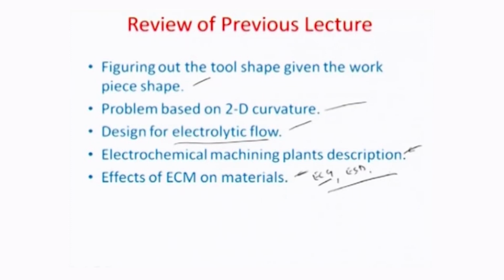After the review of these fundamental electrochemical machining processes, we will start over again and try to apply some of this technology to the fabrication of microsystems, for example microneedles, very small, superfine, high aspect ratio structures used in the area of MEMS or microsystems, which can be fabricated using such machining protocols by localized deposition of material at a certain place.